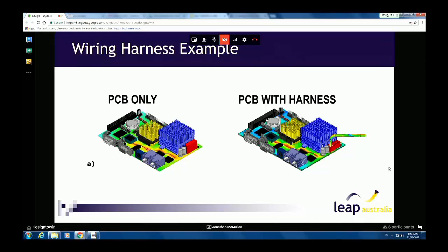But it wasn't too bad, and it was good enough to pass the first time through. Once they added this extra wiring harness, in particular this one conductor here, all of a sudden they found that this wire basically became an antenna and was very, very susceptible to receiving outside interference. And so it turns out that this is the reason why.